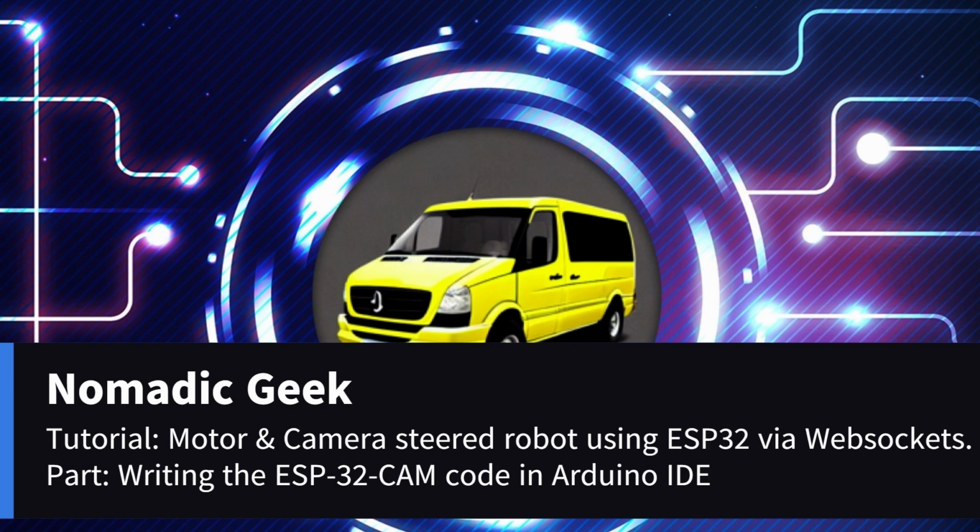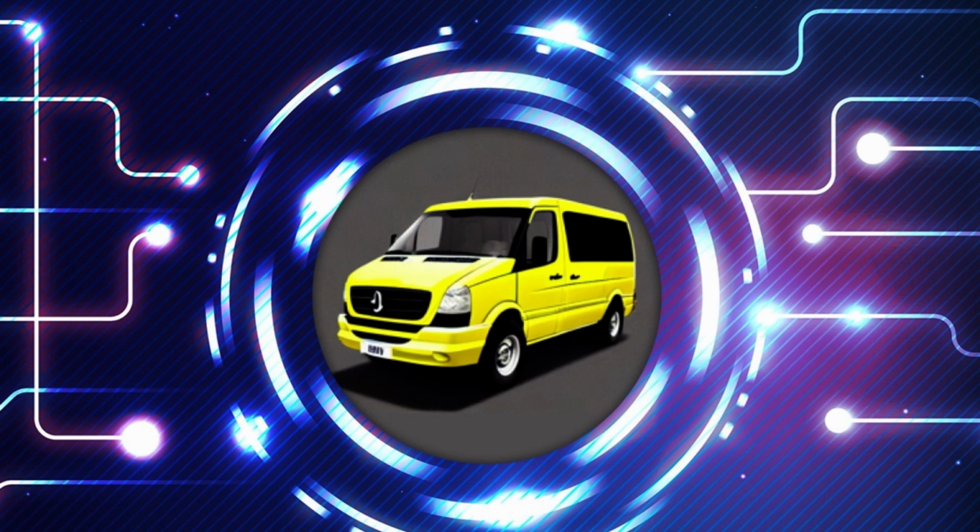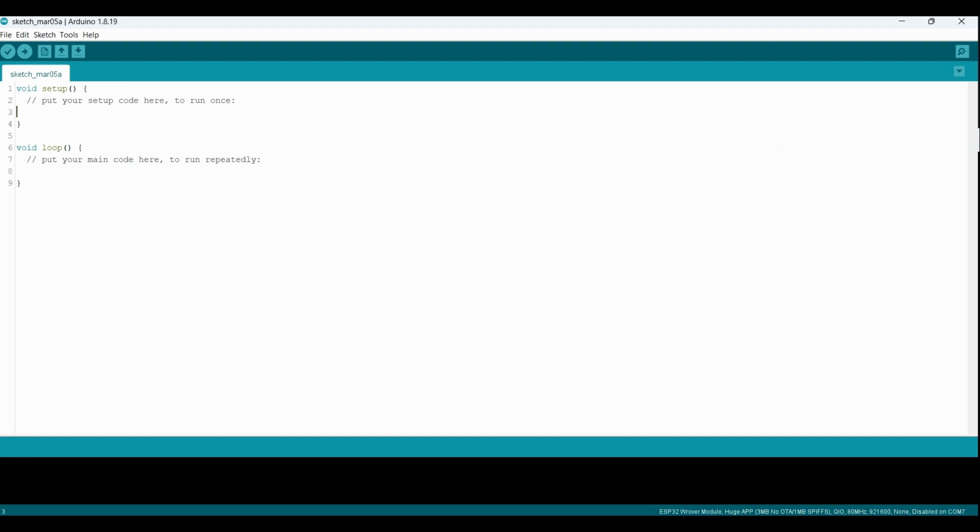Now that we have gotten that out of the way, let's dive in and start controlling the motor. First, we are going to write the code for the ESP32 powered CAM module. We will set up a WebSocket client on the ESP32 board and listen for messages from a WebSocket server. It will also control a flashlight and a stepper motor based on the messages it receives. Additionally, it initializes the camera configuration settings for capturing and streaming video to a Node.js server.